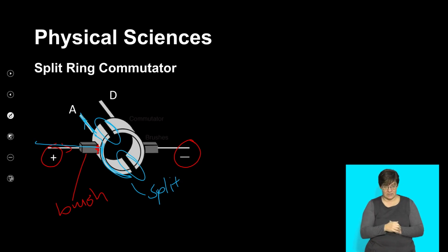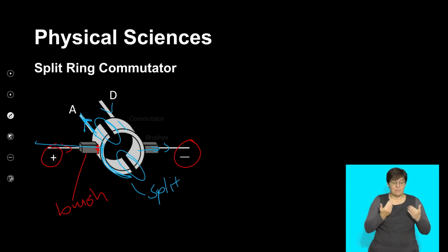And so the armature at that point is point A. The current is going to go into A. And if we look at the reverse part, over here the current is coming out of the negative. It's going to come out of D. It's going to go into that second part of the commutator, through the brushes and back to the battery. So that's how this process works, of supplying each part of the coil a different direction of current.